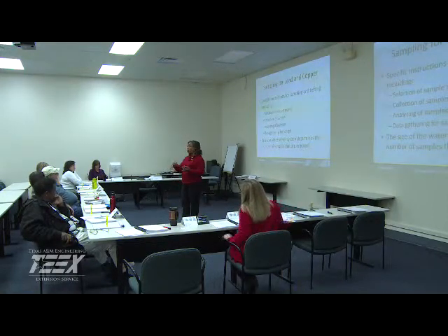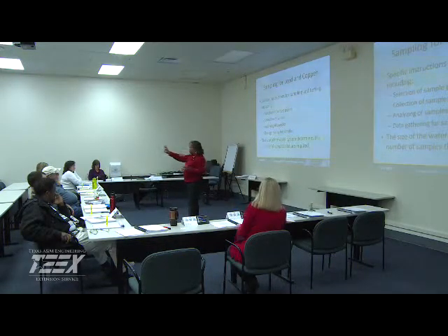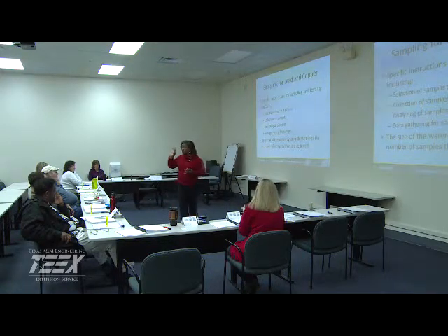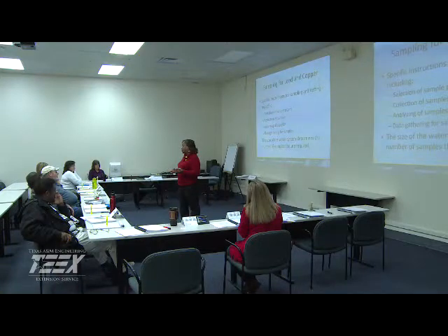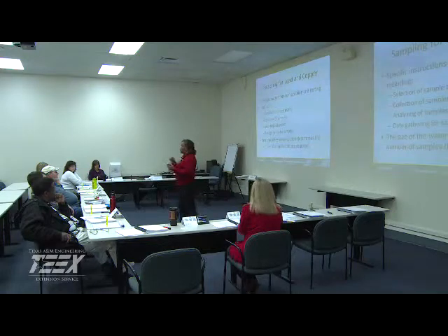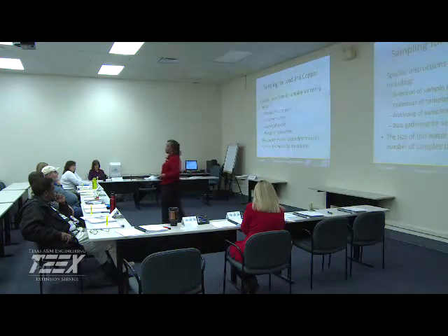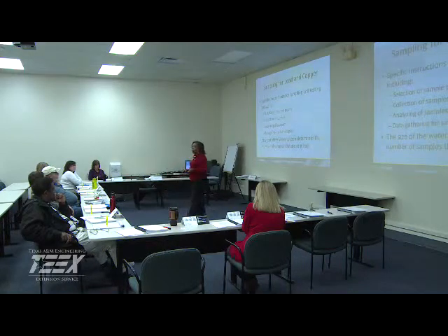So you want to make sure when you're getting your sampling points, you have representation of all. Usually there are 3 tiers that we're looking at, and you want good representation for those 3 tiers of sampling sites. Two of them deal with single residences, prior to 1982 and after 1983. A single residence is a single tap into a home, like a single family home.